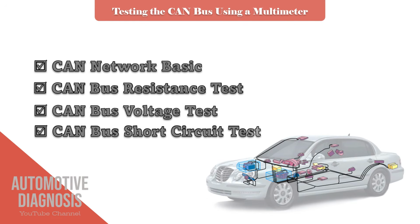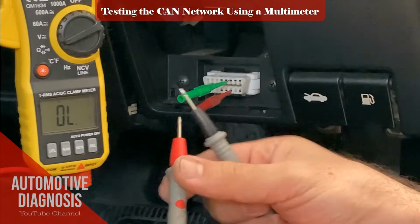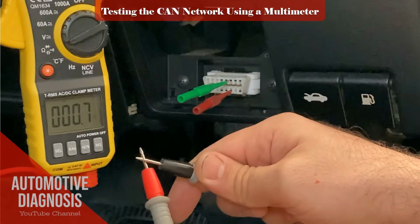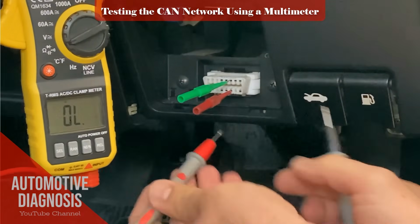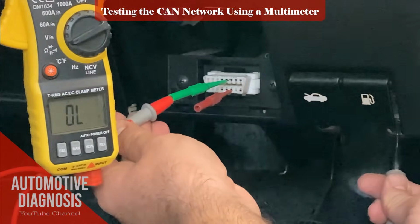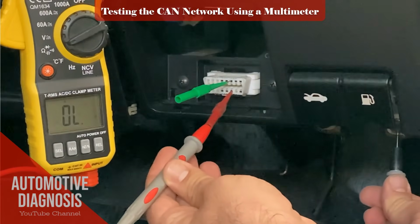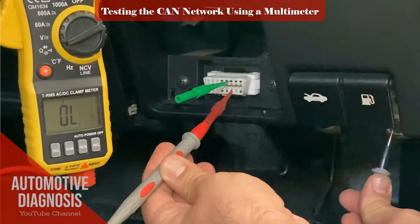After checking the voltage, you can check the short to ground on the CAN bus as well. So, turn the ignition switch off, and check the continuity between CAN high and body ground, then check the continuity between CAN low and body ground. There should not be any continuity between each CAN bus wire and body ground. If there is any, it means that the CAN bus is shorted to ground.